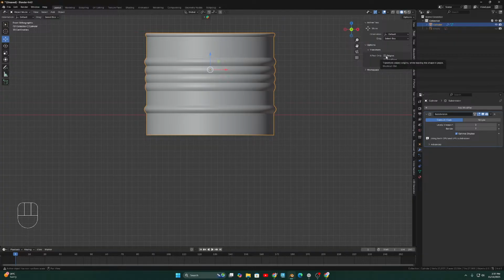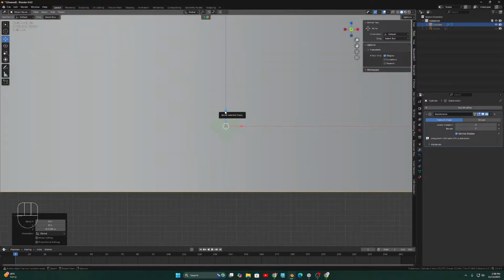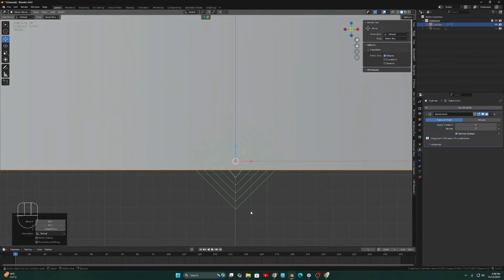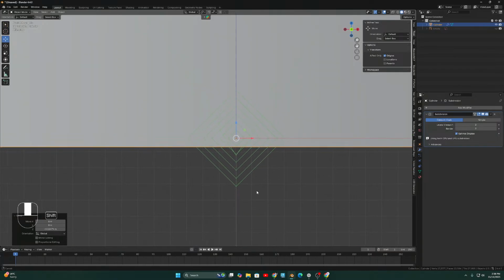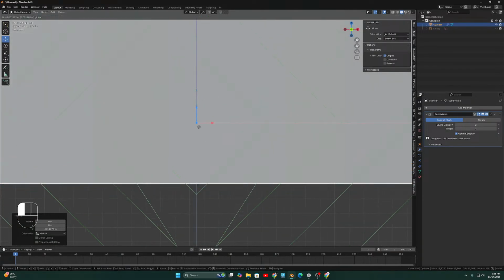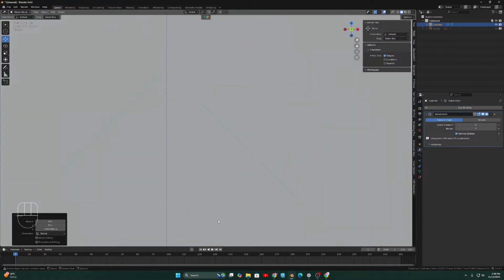How you can set the pivot, that is the question here in the current scenario. So you can see this origin option, just click on this origin. Now if you move your pivot, your object will not move, only your pivot is moving. So let's bring your pivot here, go a bit more closer, shift plus middle mouse, and go a bit more closer and add your pivot here.